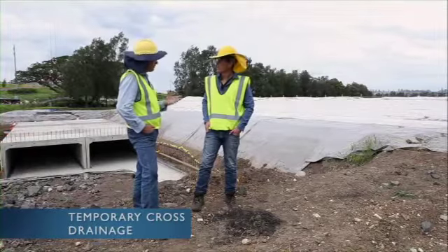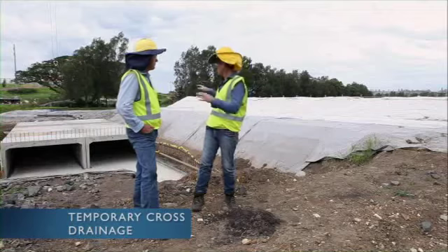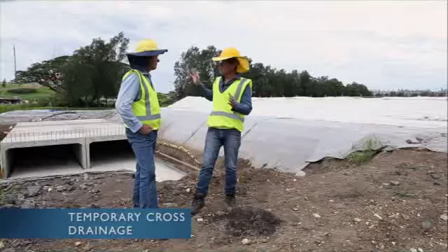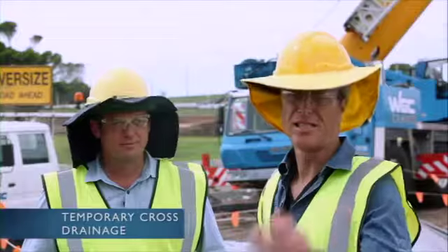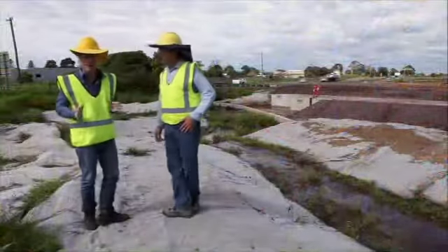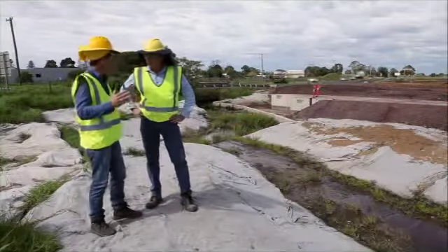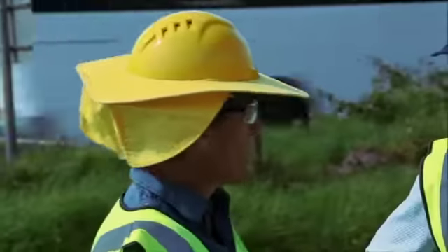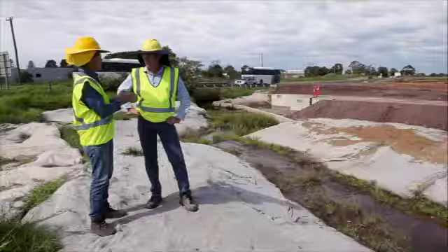So that water's not being channeled through the construction site. So those additional benefits are really around constructability, not getting delays on site, and when it's wet, getting back into those sites quicker. And this permanent culvert is exactly where the natural water flow was. That's right. Yeah, so the temporary water course goes in, a nice dry site to put the new culverts in. Workers can access the site along with their machinery, less delays. Now we've talked about temporary cross-site drainage which diverts water away from its final course, which we can see here. Chris, what's the reasons for permanent cross-site drainage?